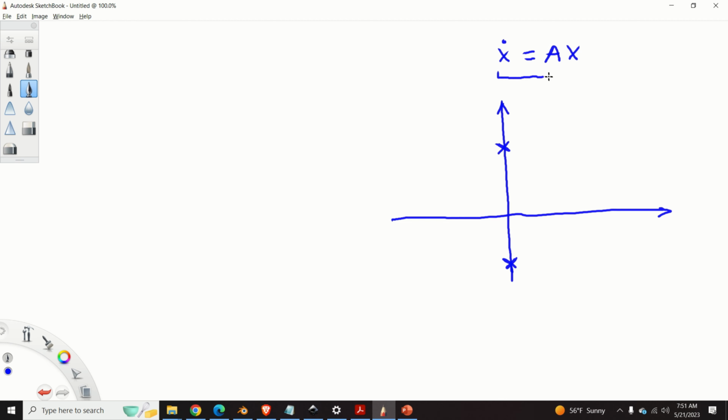Obviously, the equilibrium point of this system is stable. However, it's not asymptotically stable. In this case, you cannot make any conclusion about the stability of the equilibrium point of the nonlinear system. The equilibrium point of the nonlinear system can be stable, unstable, asymptotically stable. However, you cannot make strong conclusions.